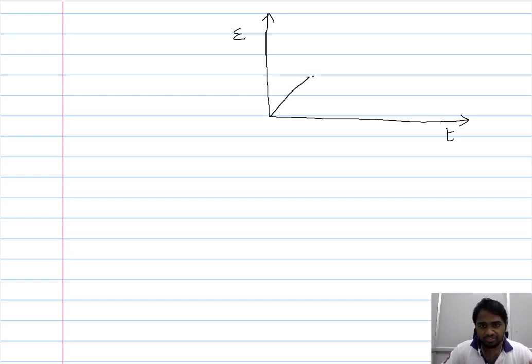You have an instantaneous creep region and a transient creep region. The instantaneous creep region is rather instantaneous. There is sort of a linear relationship between the strain and the time. And there is a region which we refer to as the transient creep region, where the rate at which the strain occurs is gradually decreasing, and there is a region wherein there is not much strain observed and the strain rate is rather minimal, and there is a final region where there is a significant increase in the strain rate and ultimately the material fails.